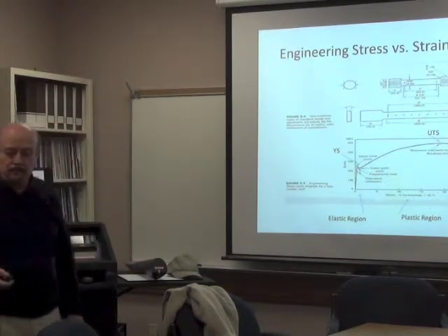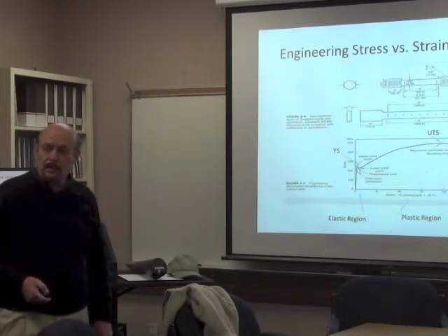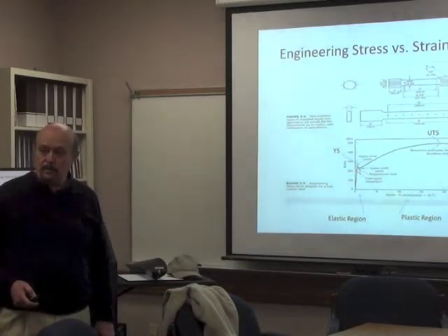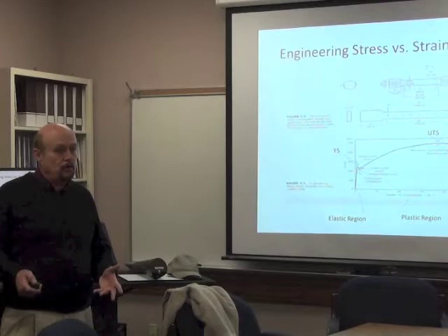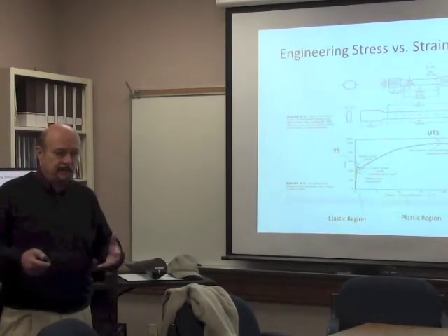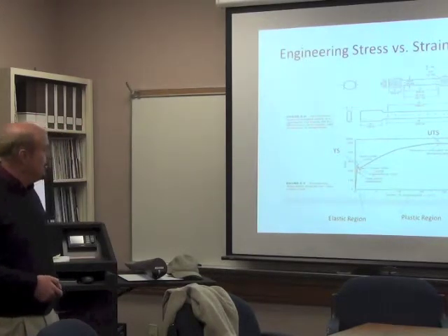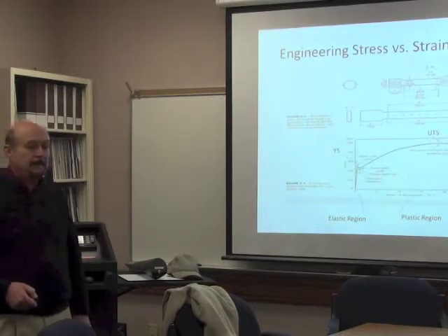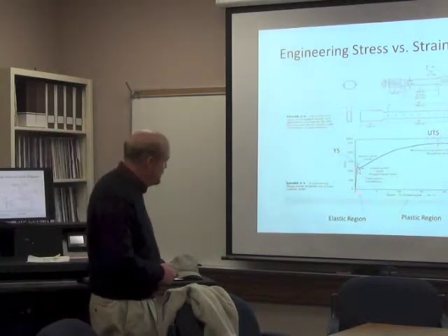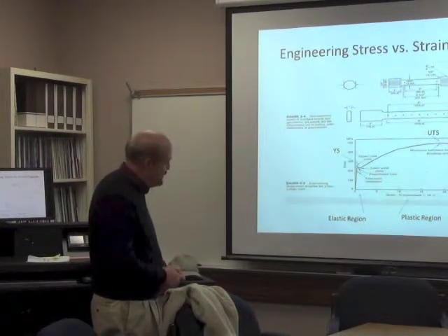For example, if you put more carbon in the steel, it becomes harder, okay, and stronger. Now the only bad thing about it is it also becomes more brittle, okay. So you lose ductility or plasticity, the formability of a material. When you add more carbon, you get more strength properties, but your ductility goes down. See, this whole region here, this is the elastic region, just this little region. All this is plastic deformation until finally it breaks here.